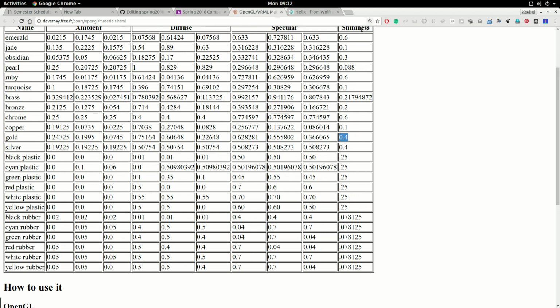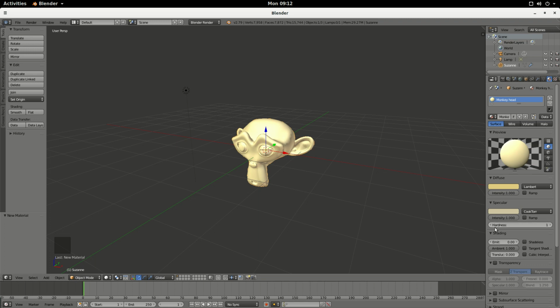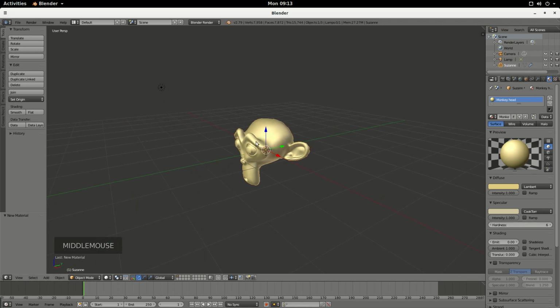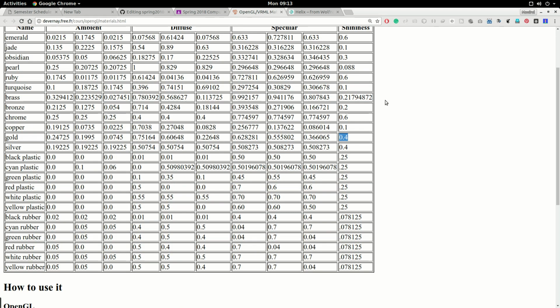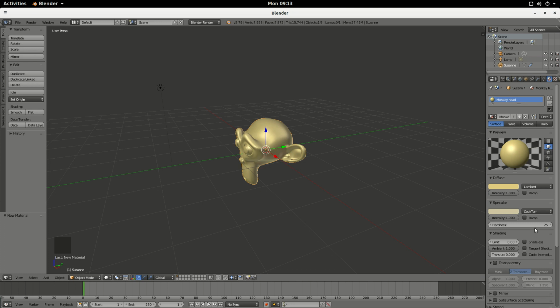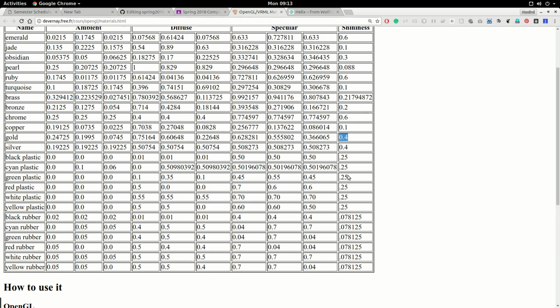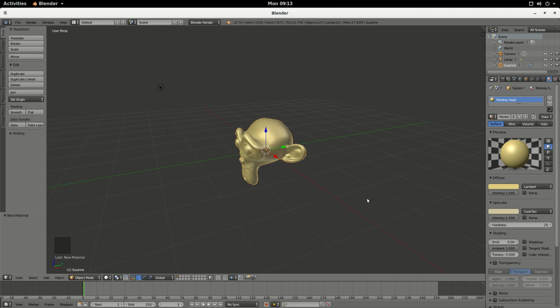Okay, if you look at all these values, you'd see that they range from 0 to maybe 1. But over here we were dealing with some integer scale. So that's why you need to account for that, and maybe get a feel of what your eye feels is the right amount of shininess for a golden material and settle for that. It would be nice if we could use this thing, but they conform to a different range. They're not in the same range. That's what I'm saying. Maybe they're in the range 1 to 255 over here, although you can go higher than that. But over here, they're in the range from 0 to 1. That's why you need to scale it up, definitely to a certain level.